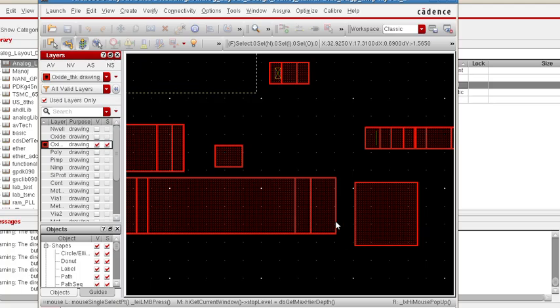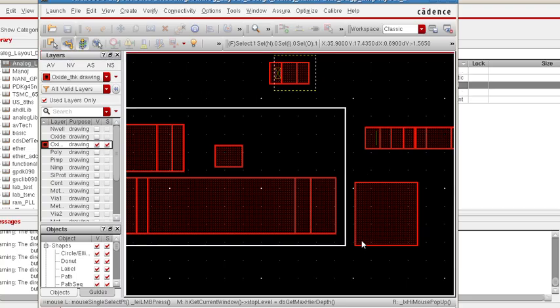So here in this video, the layout, you can see that we have two different devices which don't share the OD because of the difference in the width of OD. So these will be placed with a proximal distance or the minimum DRC. In such cases, where these two transistors or active devices need to be isolated electrically, I will be speaking about the purpose of isolation.